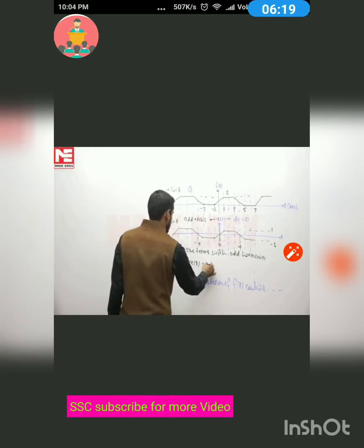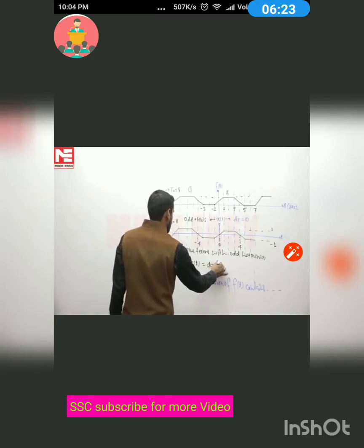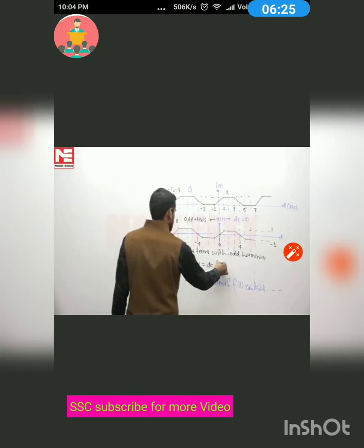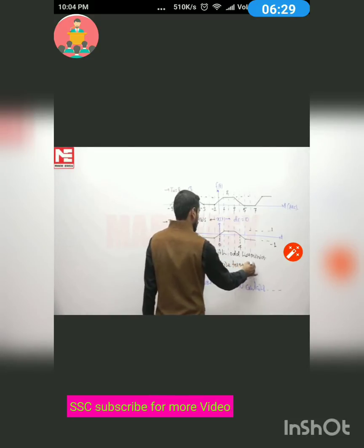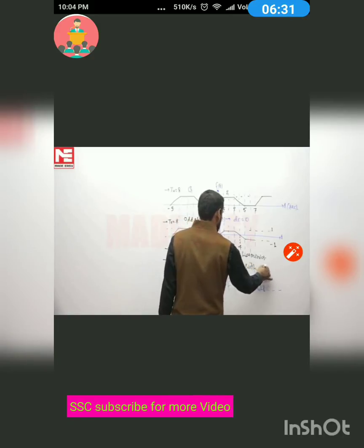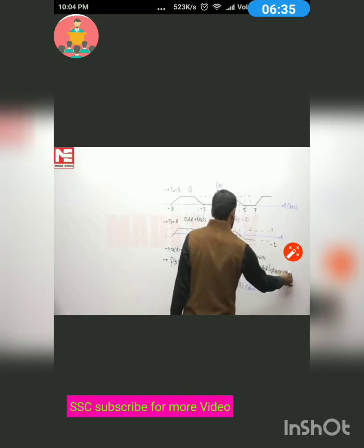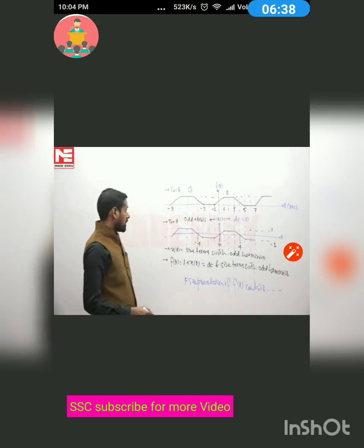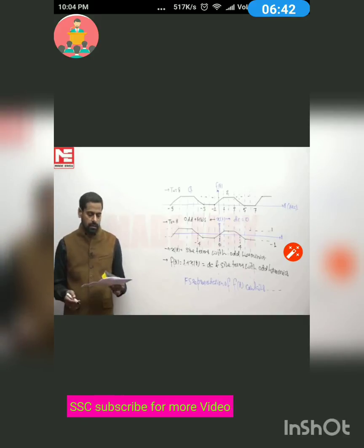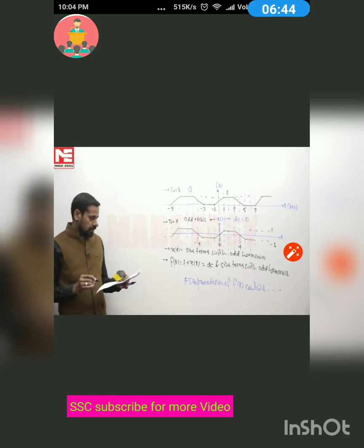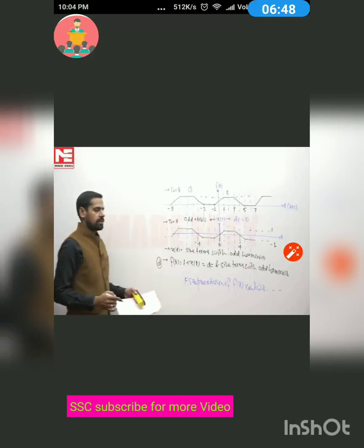So we can write down in this way: for 1 we can write DC, and the expansion of x(t) contains sine terms with odd harmonics. Therefore, the expansion of the given signal f(t) contains a DC term and sine terms with odd harmonics. If we look at all four options, option D will satisfy this result.